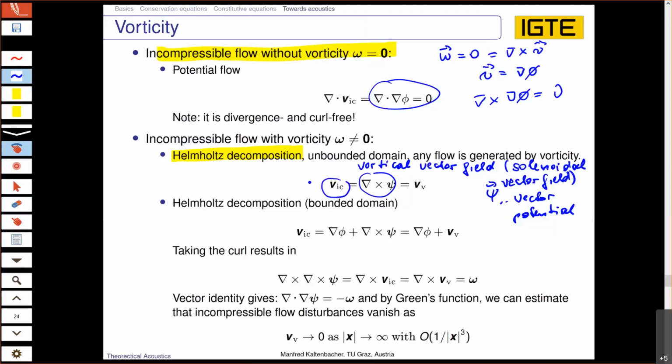Okay, so the Helmholtz decomposition in the sense of an unbounded domain is as follows, as written down here, that we can decompose, as I have shown you just before, into an irrotational field described by the gradient of a scalar potential, which will be for us at the end such a potential flow, or if this is changing, then we even get the relation to an acoustic wave, and the curl of a vector potential, which we directly relate to the vortical structure.